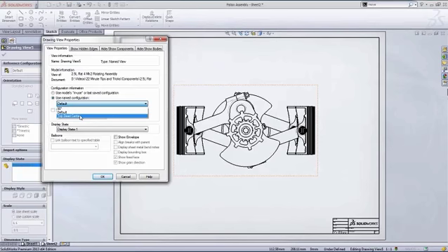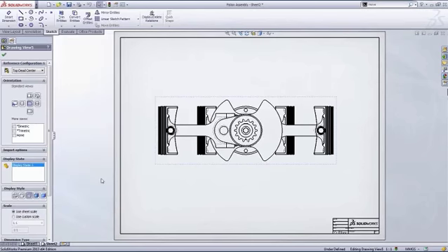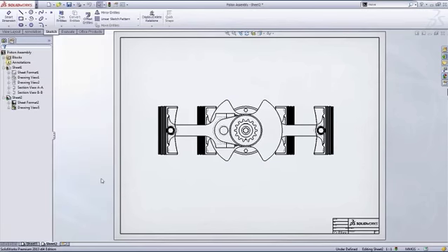For reference, top dead center is when piston number 1 is all the way up or extended, depending on how you want to look at it. When I choose top dead center, SOLIDWORKS will redraw the view using this configuration, regardless of where all my parts were in the configuration we were working on before. This ensures that all my components look nice on the drawing, but I can also dimension them much easier this